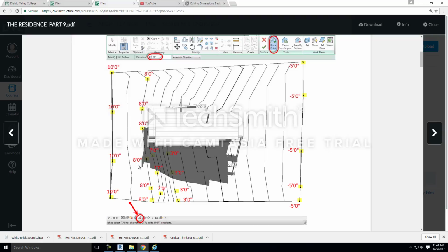The most important part is to think about where the topography meets the building in certain locations. Once you're done, you'll probably have to go through, click on the topography and edit it at a later point, because you're going to realize that the topography is like 2 feet below your door or something like that. So you'll need to go in there and adjust the points as necessary, okay?